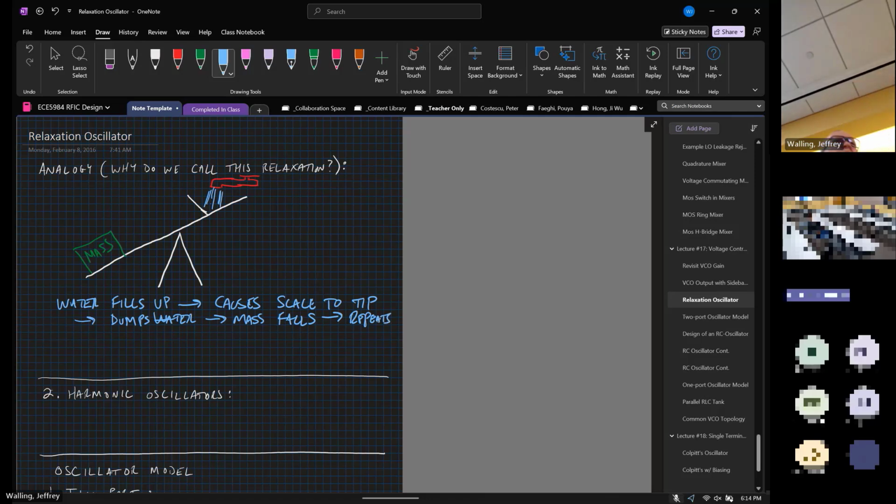Okay, now you might also imagine why this thing would be noisier than other types of oscillators, at least with respect to phase noise. In the oscillator, if I have a signal, a clock signal, phase noise is basically measuring the uncertainty of when the edge of the clock arrives.